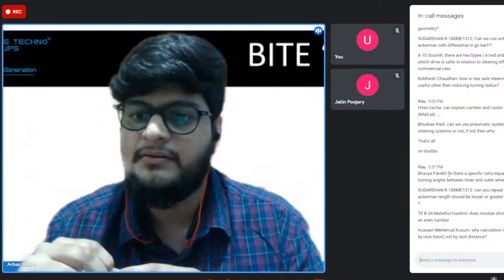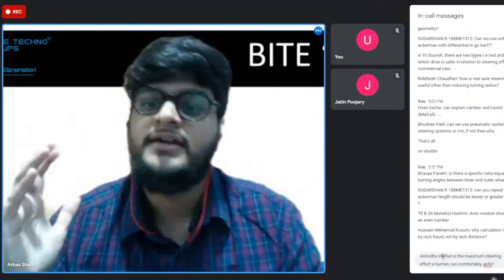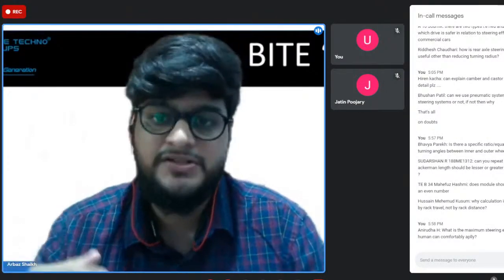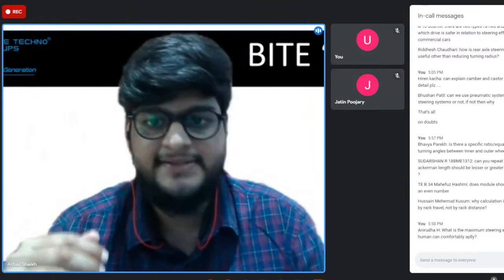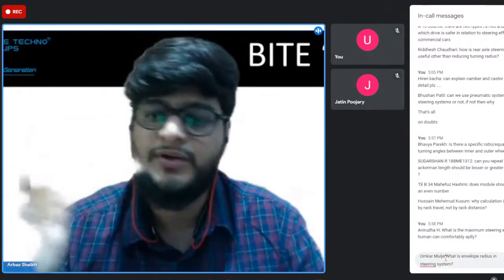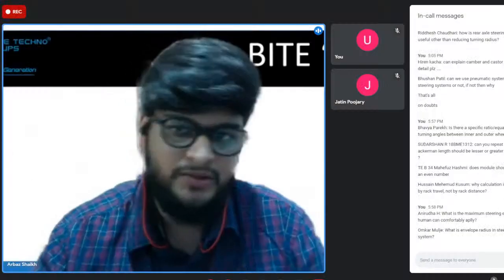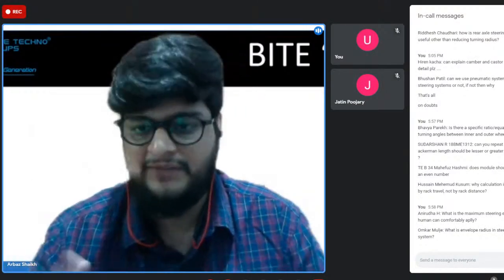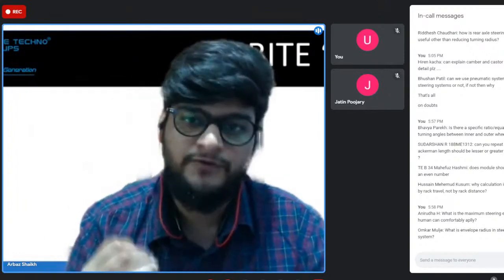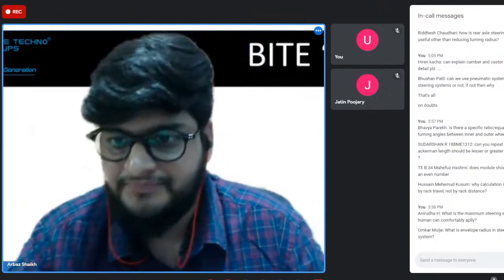Okay, Mahefuz is asking, does module should be an even number? No, it should not be an even number. It's never like that. Modules are predefined by manufacturers and engineers. Like I said, it starts from 0.2 and goes beyond 10, 20. I don't know what the upper limit is, but you can find it in intervals like 1, 1.5, 2, 2.5, 3, 3.5, 4, 5, 6, 7, and so on.